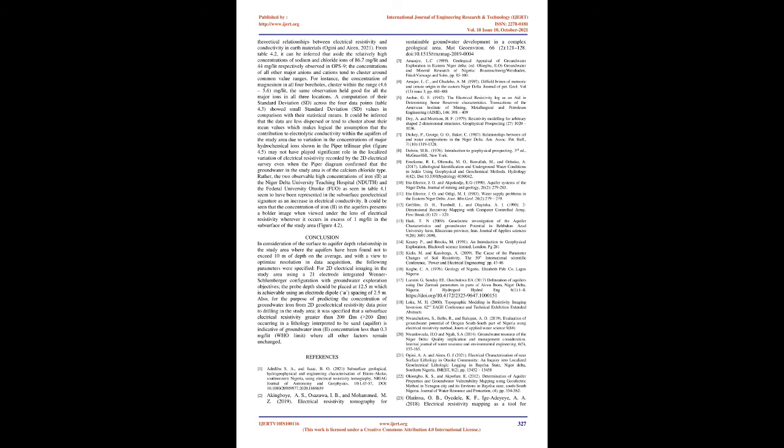The 3D resistivity surface extracted at the horizon containing the major aquifer, Figure 4.4, showed major resistivity contours of 50 Ωm, 100 Ωm and 150 Ωm, with the 150 Ωm closures forming domes while observable resistivity structural depressions occur between the 50 Ωm closures. Figure 4.3 correlates resistivity to observed lithology with respect to depth in the Niger Delta University Teaching Hospital, NDUTH, study location.